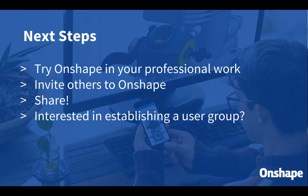Also, if you haven't already, we really encourage you to invite others and share your document. There's a big share button in the top right corner. You hit share, you enter their email address, define their permissions, whether you want them to be able to edit or just view, and then hit share. Even if they don't have an Onshape account, we create one on the fly and then send them a link. So it's very easy for you to share with someone, and then they can jump in and look at the same exact model as you at the same exact time. If you give them edit permissions, you can even edit the model at the same time. You could build assemblies together. You could edit parts together.